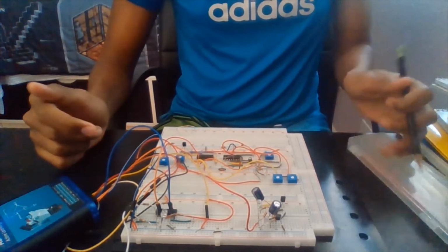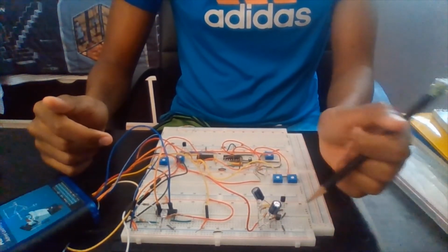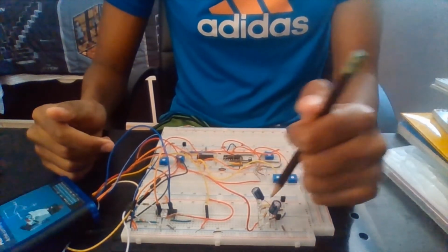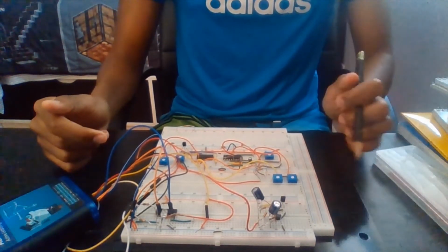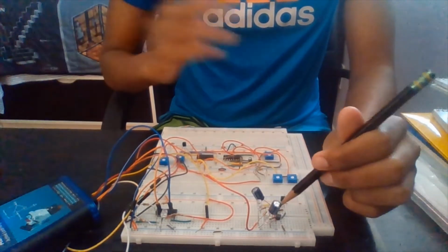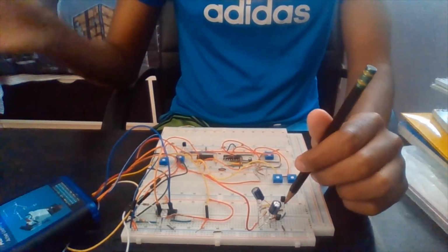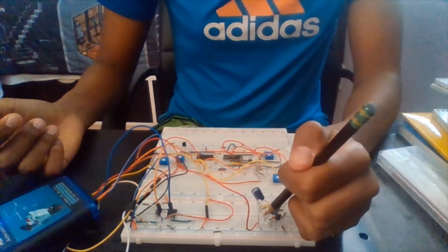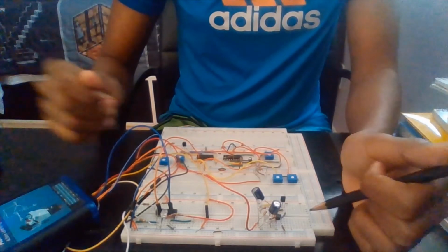And just talking about this third subcircuit over here, I use two 100 microfarad capacitors, two 33 kilo ohm resistors, and two NPN transistors, which essentially oscillates the LED into sort of like a square wave, where when one is on, the other is off, and it's not really increasing in magnitude. Ideally it shouldn't, but in the Scopy graph that I'll be showing you shortly, it actually does increase, so it behaves more like a sawtooth wave.